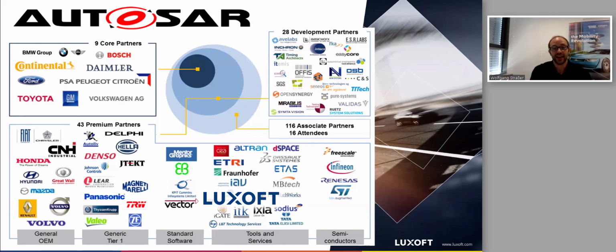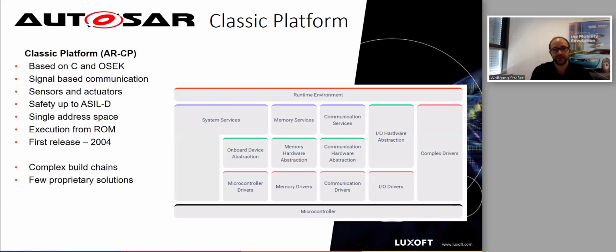So now, what does the AUTOSAR group actually do? The AUTOSAR group has a target to define standards for the automotive world. The main contribution of the AUTOSAR group so far was the AUTOSAR stack, or how it is called now, the AUTOSAR Classic platform. The AUTOSAR Classic platform is a software framework that is used within vehicle ECUs. Basically, it provides some software modules for common core functionalities of an ECU, like communication, memory access, cryptographics, or also diagnostics, and others.